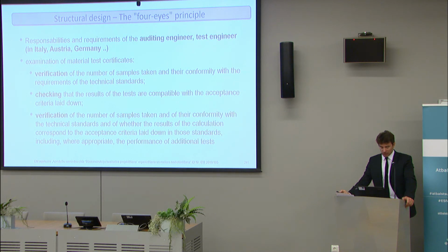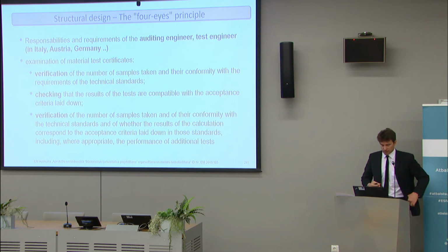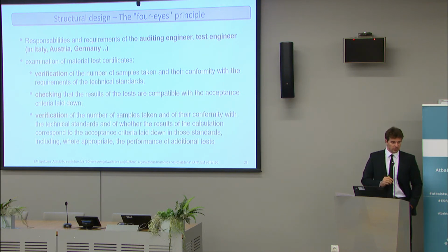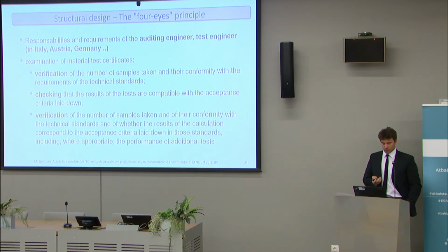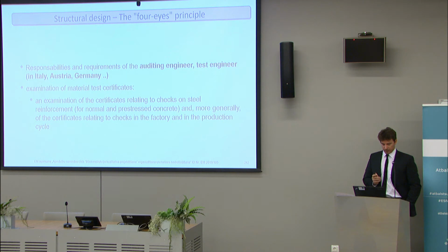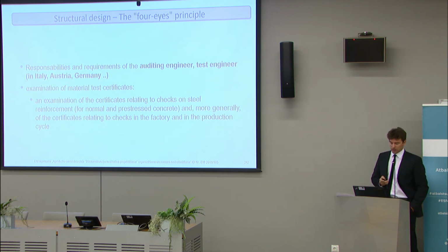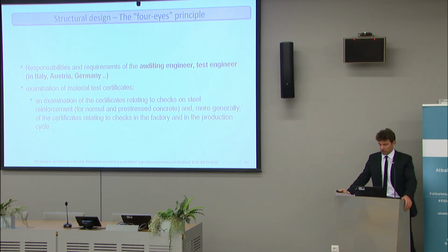So verification, checking, and the number of samples also. For concrete, it is very important that this is performed as specified in the technical standards. Yeah, we have a strict internal Italian regulation about how many tests and how many controls on the site, and before materials are sent to the sites. And this is also something that the auditing engineer has to examine in the phase of examination. Examination of material test certificates during the checks of steel reinforcement and, more generally, checks of the factory and production cycle.